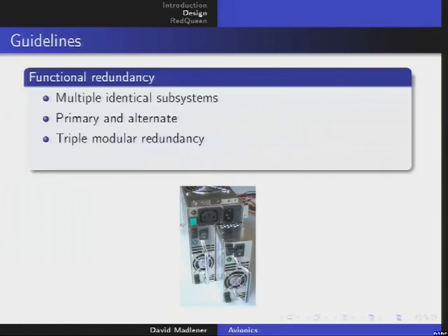But this voting logic is normally made of very resilient devices. And one important thing, use different approaches. If you have, for example, an avionic performing some task like attitude control, make 2. Envision 2 teams building the same thing, but on totally different devices with totally different programming languages doing exactly the same thing. Then they won't fail at the same moment, normally.